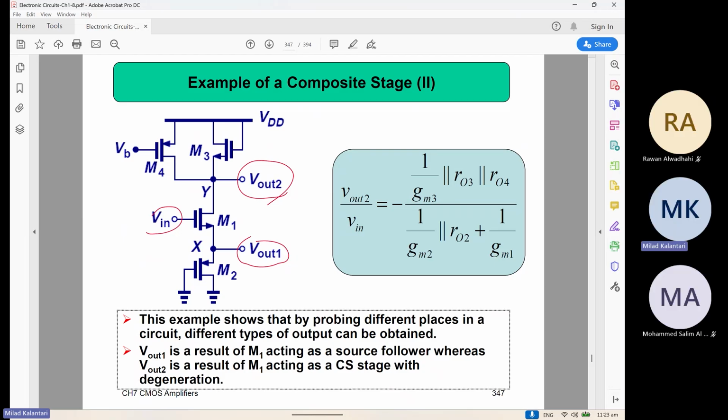So it doesn't matter, you just replace each of these dummy devices underneath as a load resistor. So this should be something like 1 over GM2, right? Because we are looking at this device as a source. So the impedance we are expecting is 1 over GM2. For the M3, again, we are looking at the source of the device, so the impedance is also low, like 1 over GM3, depending on the current of it and the GM value, right?